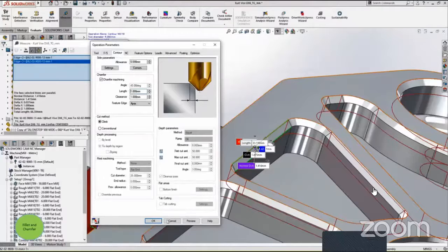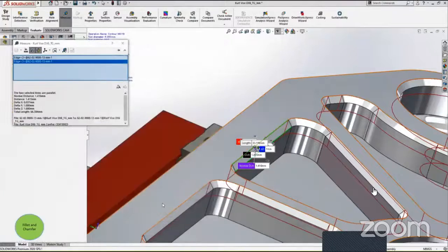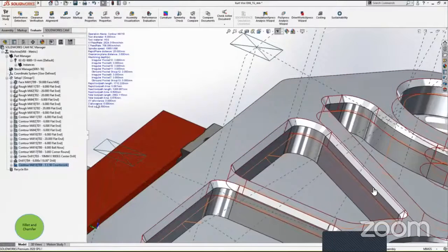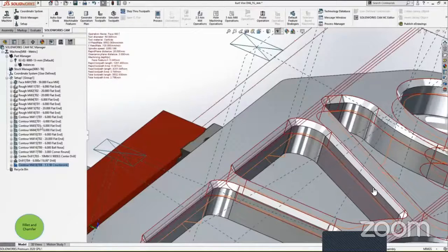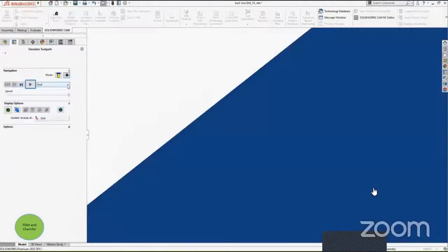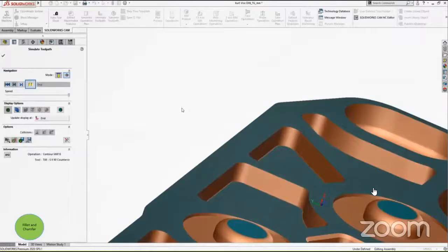So, okay. One more thing is the clearance. I will use clearance 1 and then feature edges outer edge. Click OK, and then generate the tool path. Now the tool path has been generated and it's also being shown on the screen. We can simply drag and drop under the contour milling section and simulate the result in turbo mode.